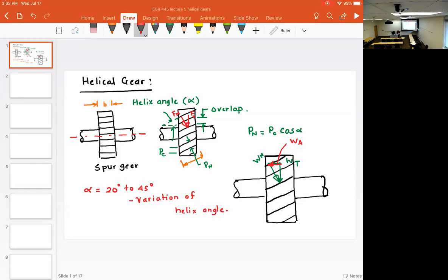And addendum, which is the distance from the pitch circle diameter to the tip of the tooth, is usually 0.8 times module. Dedendum is usually 1 times module, and then the tooth depth is 1.8, and minimum clearance and thickness. So these are the standard proportions.